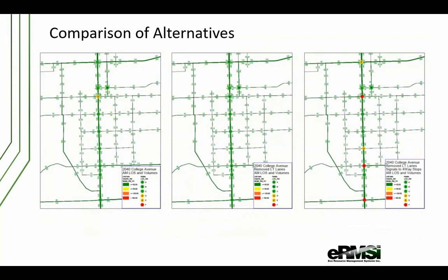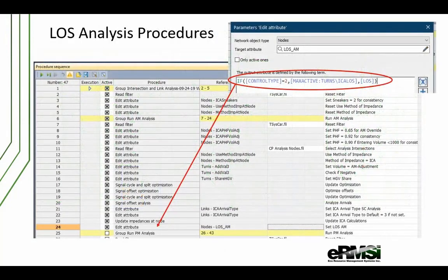And so we could recommend changing those left turn lanes into bike lanes, or using the space as bike lanes, actually doing a little more calming instead. Okay, one thing we did here, those of you who work with the HCM know that with most of the intersections, you use average LOS. For stop signs, partial way stop signs, you use the worst turn LOS.